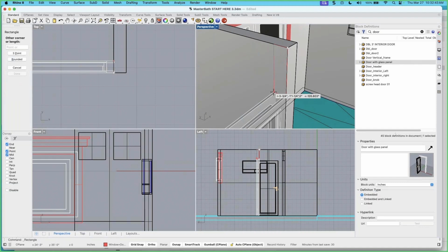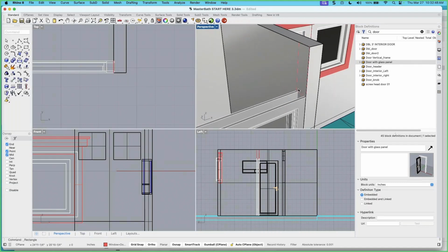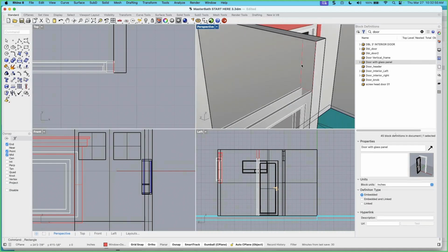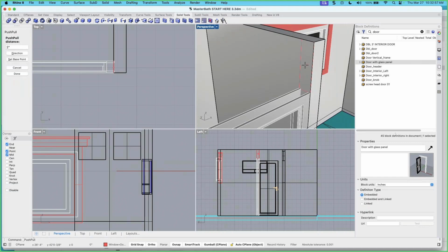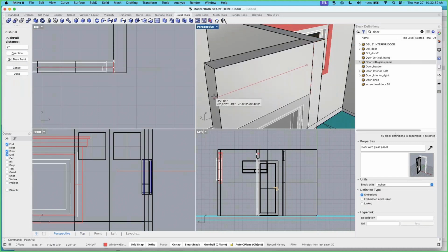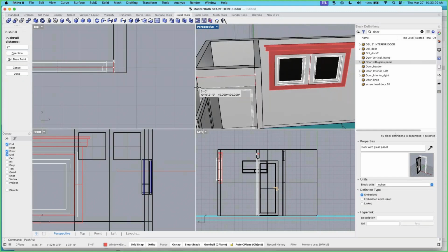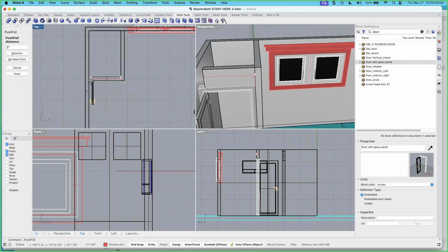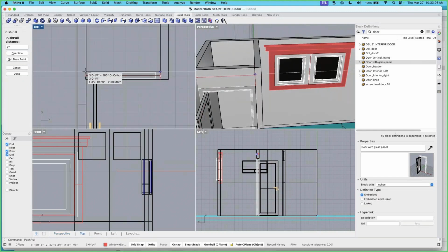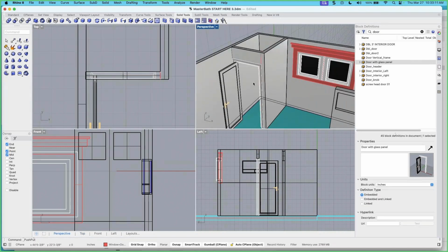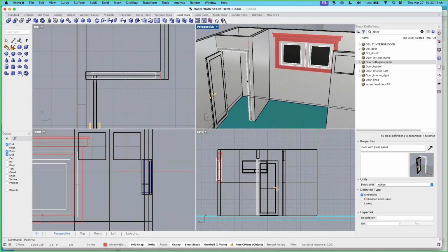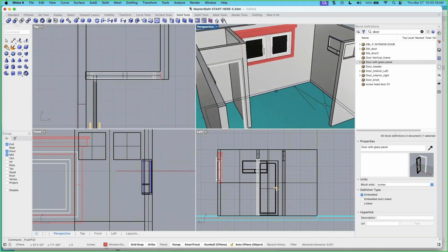And this will be used to pull the wall across. So now that I have that rectangle on that surface, back to solid tools, push pull, pick on that area, and just like we were out in the field building this, we're going to make sure that that is a closed wall. Beautiful. And all that was done courtesy of push pull.